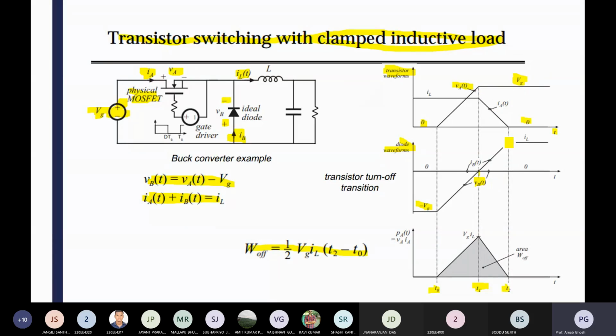Okay, again zero. Initially, when the diode is reverse biased, we get zero current up to this position. So the MOSFET will reach the maximum voltage, and up to that time the current is zero because the diode is reverse biased. So now the voltage is zero, and the current is also zero. After that the diode is forward biased and your MOSFET goes off.